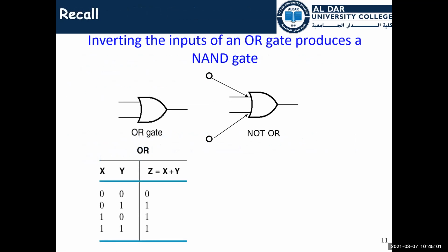As I told you, you just sketch your logic gates using AND, OR and NOT. Then start to convert to all NAND gates.